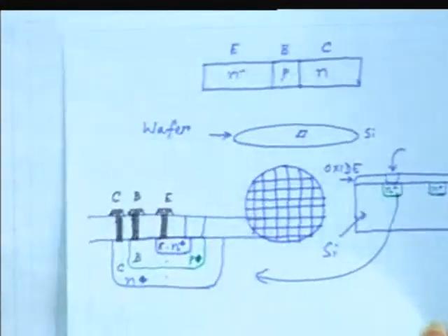But nowadays the digital technology, they are mostly using so called CMOS logic. So what is CMOS logic? You are using MOS transistors for its fabrication. So why you are using MOS transistor? I think some of you are already aware that MOS transistors are consuming much less power. Okay, so what is the reason? Reason being the circuit topology is such that the short circuit current is almost 0.